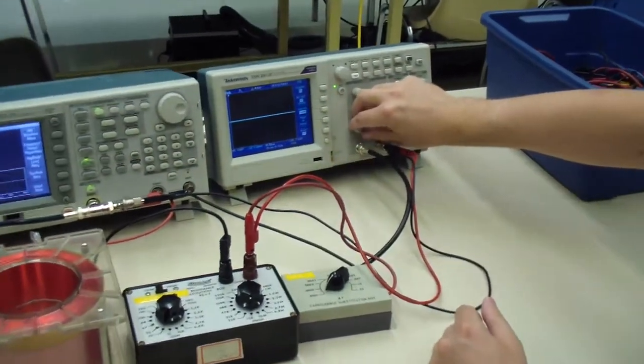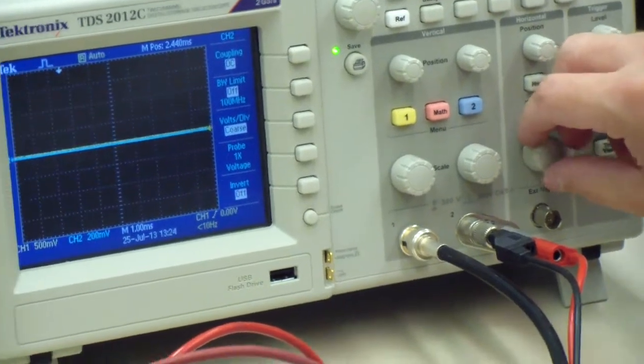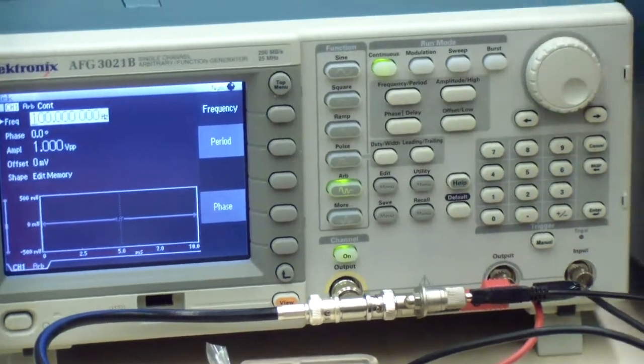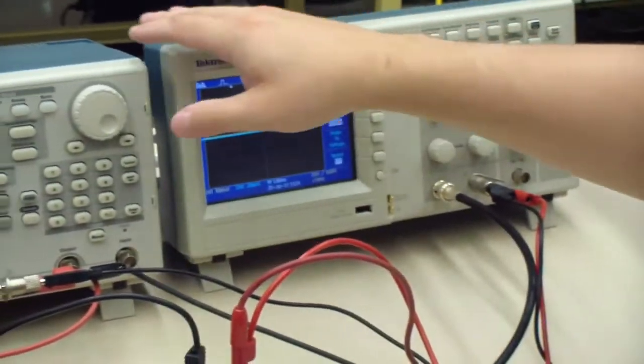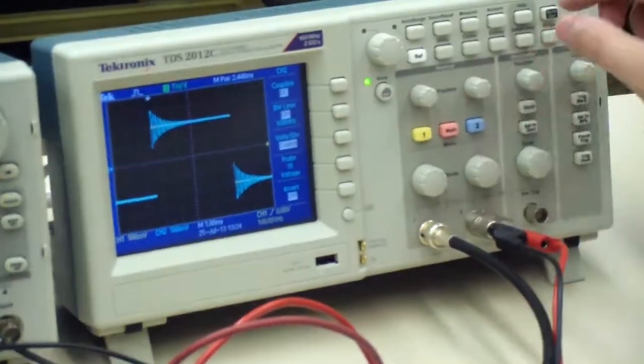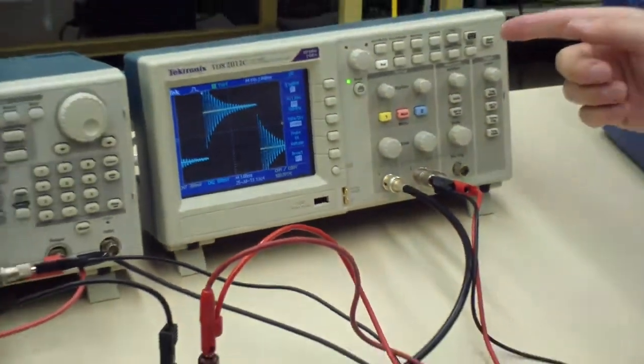Begin by adjusting the oscilloscope channel levels and timescale so that you can see a signal. Ensure that the function generator is putting out a square wave at a frequency significantly lower than the natural frequency of your circuit. If all goes well, you should see an oscillatory signal that is high in amplitude when the square wave switches, but rapidly decays.